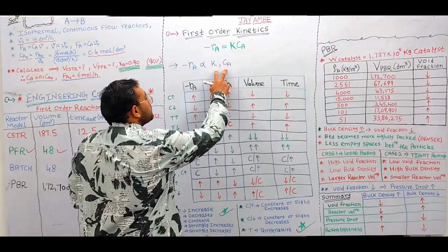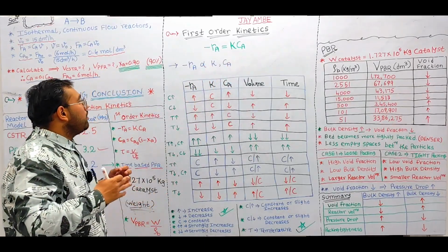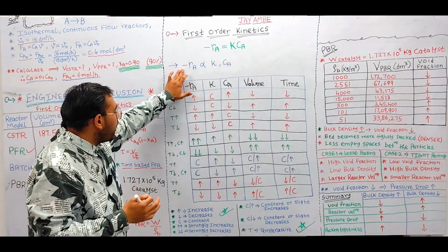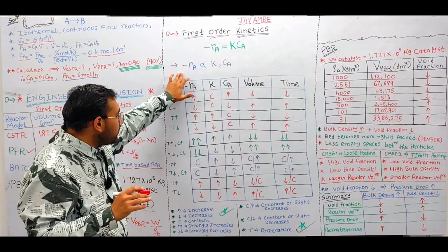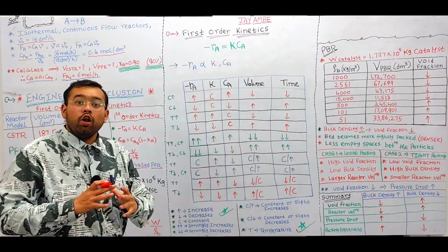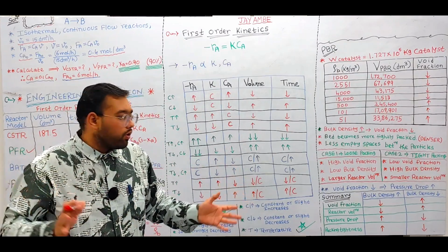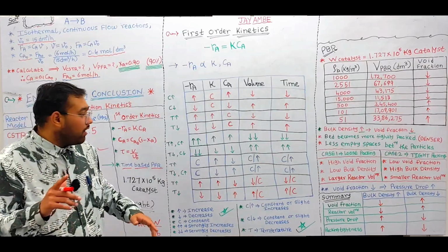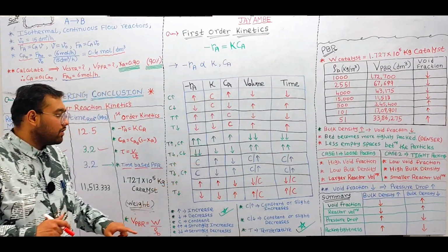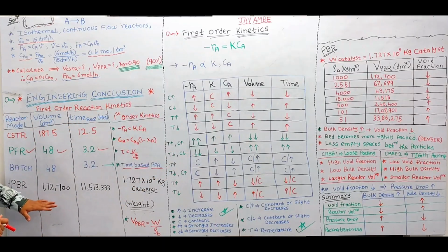due to the simultaneous decrease of the concentration and the reaction rate constant, the reaction rate also strongly decreases, right? Which results in the requirement of a larger reactor volume. The reactor volume will become so large and will require a larger reaction time. In this case we can compare with the packed reactor, right?